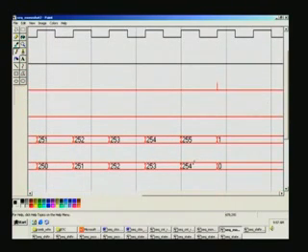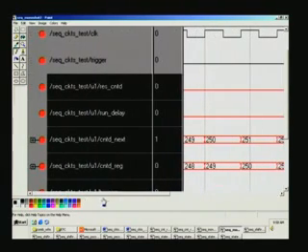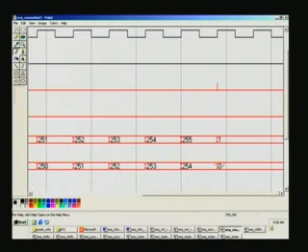What is shown here is the counter D reg, that is 254. After 254, it is incremented to 255 actually, right? But you see only 0 here. What is happening at that split second, you can see a very narrow pulse here. This corresponds to reset counter D, right? So follow it carefully here. So what happens when 254 is equal to 255, it goes for a very short while here.